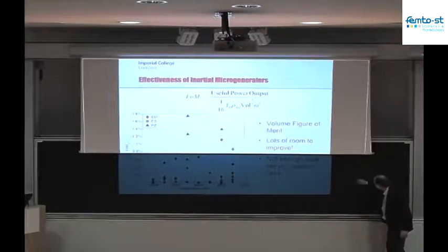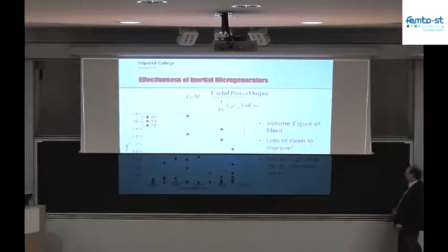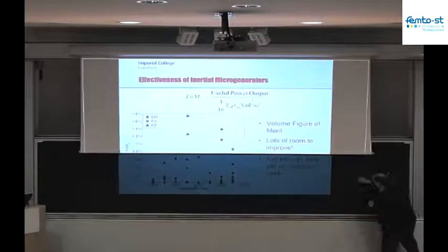So I end up with, to a first approximation, my sine wave has gone from this to this. And if I add in the correct amount of third harmonic, what I'm able to do is effectively flatten off the top of this waveform so that instead of doing this, it does this.